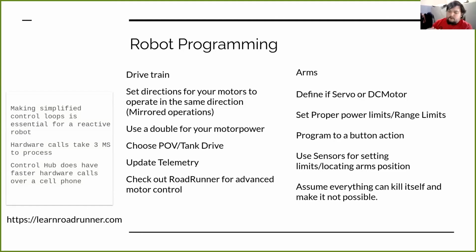And so let's say you want to update your hardware speed. Like you have 4 drive motors and you want to update that. And you also have a sensor that is going to bring back telemetry. That turns into 5 different calls, right? And so you have your 4 motors and 5, all of a sudden that's 20 something milliseconds that is transpiring to do that action.